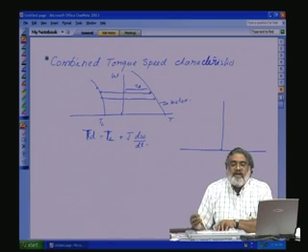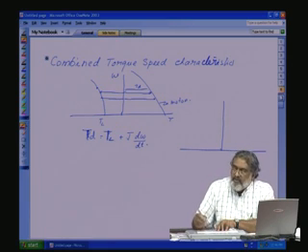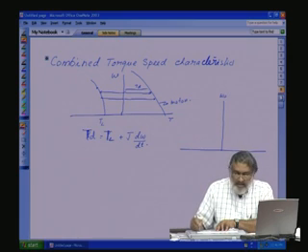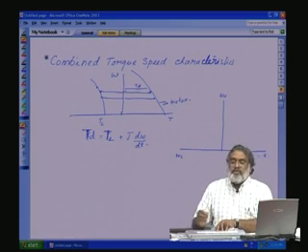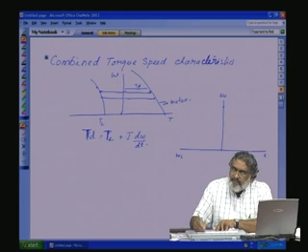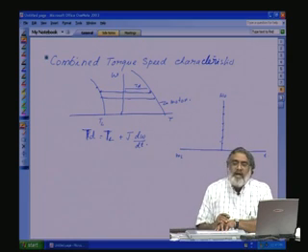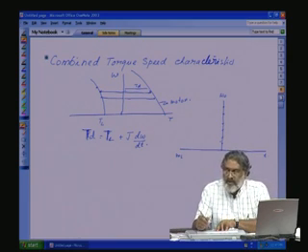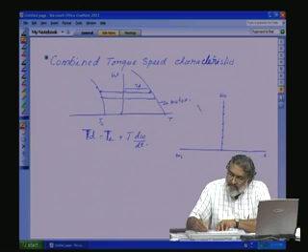This is omega 0, this is ML, this is our time axis. So, drive the system for various speeds of operation. Take 5-6 points, drive the system and find out the load torque required. So, you plot the load torque against speed.